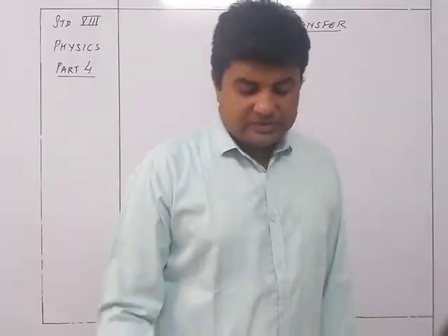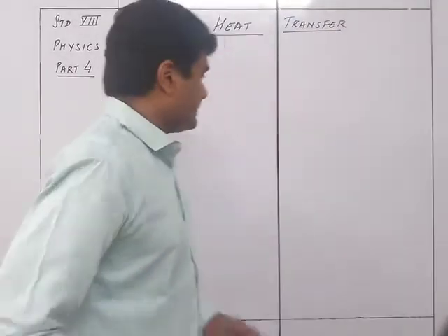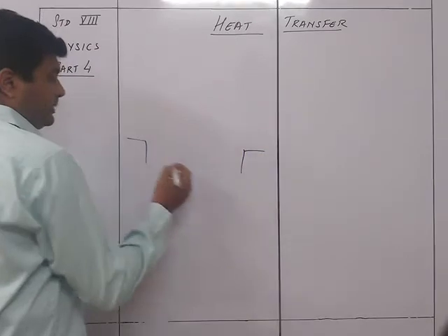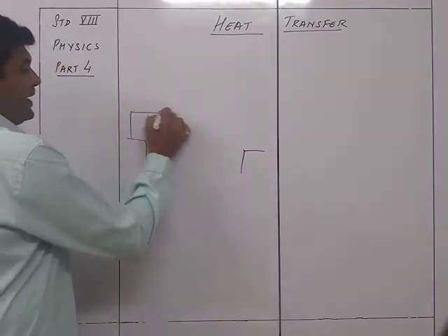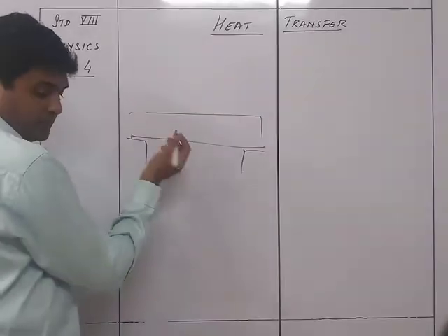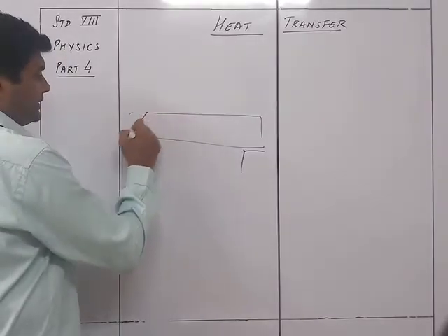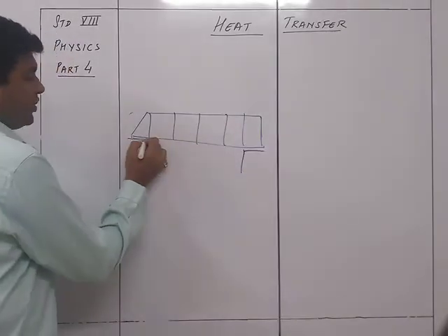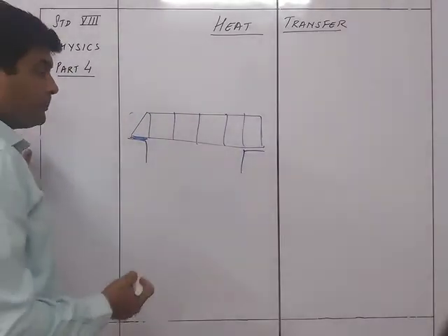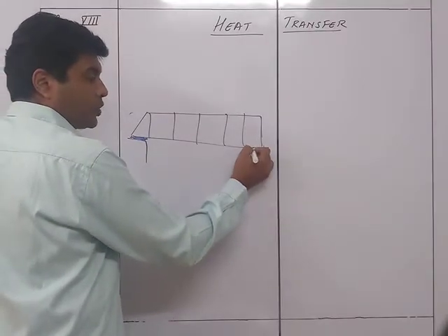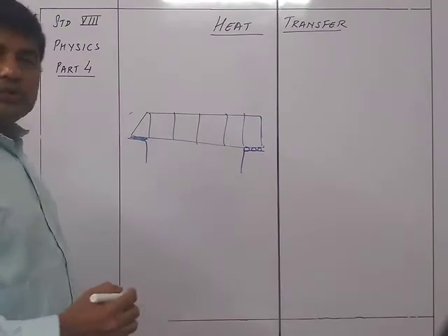So what they did was that the bridge was made in such a way that if this is one end of the bridge and there is another end of the bridge, so the bridge was made over here like this. So this is the bridge what they made. Now over here this was fixed. Okay, this part was fixed, but over here, instead of keeping it fixed to the ground, they had put rollers over here. Now what is the use of the rollers?